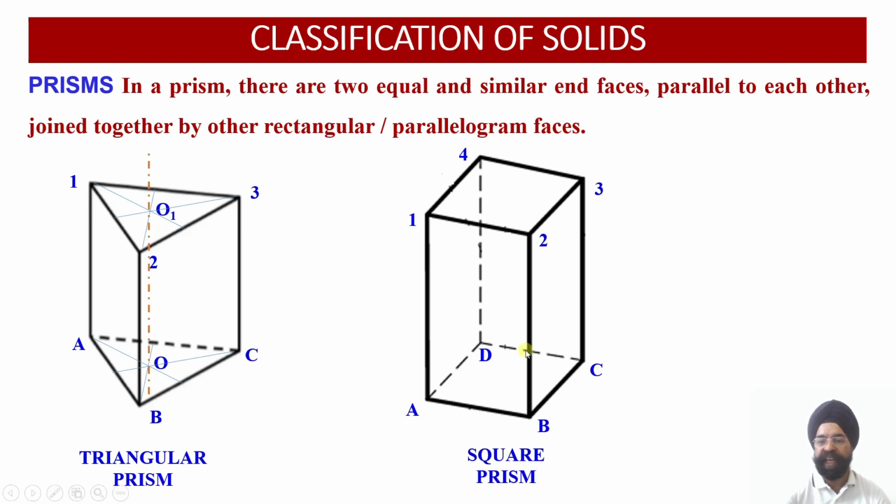Now let us work out the center point, or the axis point. For the square or the rectangle, it is very easy. Find the midpoint of AD, find the midpoint of BC. So this is the midpoint of BC, this is the midpoint of AD. Draw the axis line passing through these two midpoints. Similarly, find out the midpoint of AB and the midpoint of CD, and once again draw an axis line passing through these two midpoints. Wherever this axis line and this axis line coincide with each other, you get the center axis point.